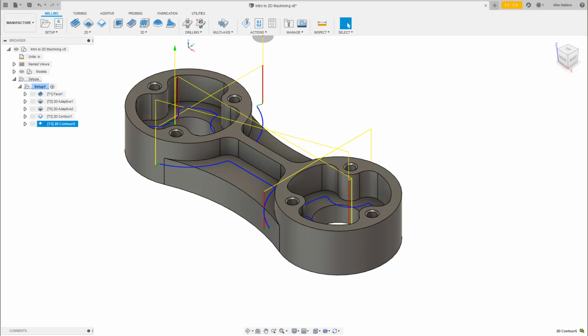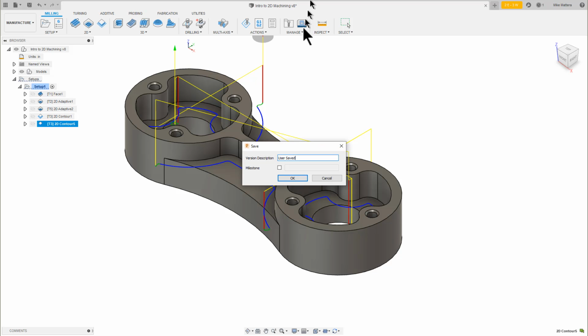In this lesson, we learned about how to copy an operation, duplicate an operation, delete an operation, and create a copy using derived toolpath. We reselected the geometry for the open and closed pockets, selecting edges for the cutting boundary, and we took multiple finishing cuts across the profiles. Feel free to simulate this as we did in the previous lesson. Press Ctrl S to save the part, Command S on the Mac.